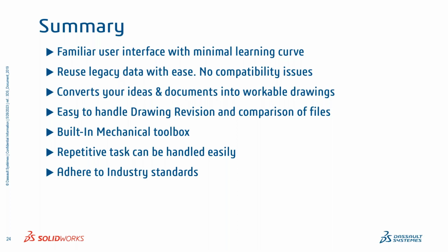When I say repetitive, I mean repetitive tasks. You can make use of the block functionalities or the custom block functionalities as well. You can make use of run and record macros. If you're doing automations in DWG drawings, or you're repeating the same number of steps, you can create a macro and run it. It goes for Lisp also. If you are using existing Lisp programs, you can bring that file and use it in DraftSight also. There will be no issues at all.